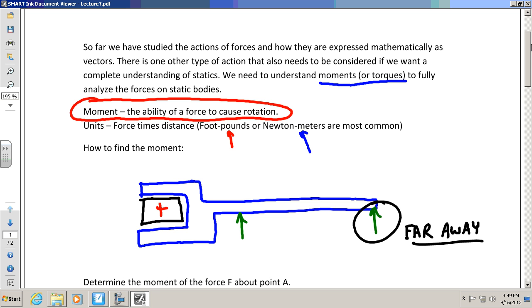Now, if you have a wrench and you want to get more moment out of it, why don't they just make wrenches super long? Sometimes you don't have a lot of room. Yeah. Anybody know else why they don't make, if you get more turning power with a wrench, 4-foot long wrenches? They'd probably break, yeah. And you don't need that kind of torque.